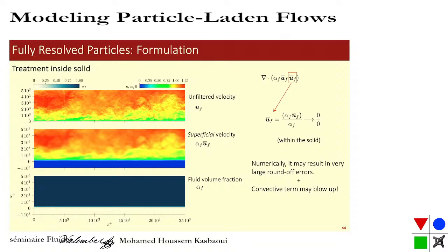Now, if you're saying, what if I have an implicitly defined filter size based on the grid, so that when I refine locally, I also refine my filter size, now you run into a different kind of issue, which is commutation errors. The equations will look very different when you have a filter size that varies with space. I think those errors are going to be very large in the case of AMR, because you do this coarsening and refining very aggressively. It's not easy to deal with.